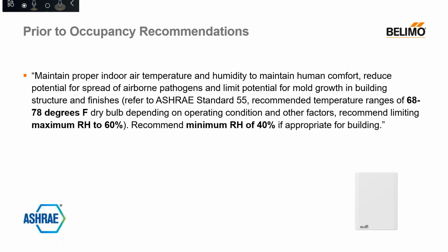There is a recommended temperature range of 68 to 78 degrees and a relative humidity range of 40 to 60%. The reason is to maintain human comfort while reducing the spread of airborne pathogens.